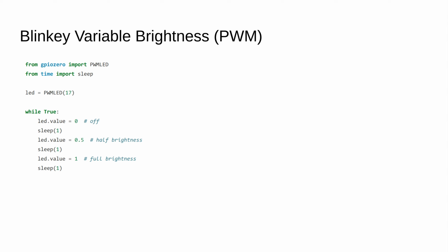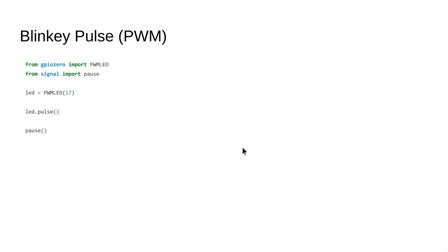Something that we get at a lot of workshops is that you've got to stop the program running before you start the next one. A lot of people say, I've put this in, but it's doing exactly the same as the one before. So it's the old program still running. You just stop it running in the Python console that's running from Thonny. And then the other one is we can literally use the pause function with the pulse width modulation as well. That one's like a pulse, in and out, like a breathing lung. The light just comes on and fades like a breathing lung.